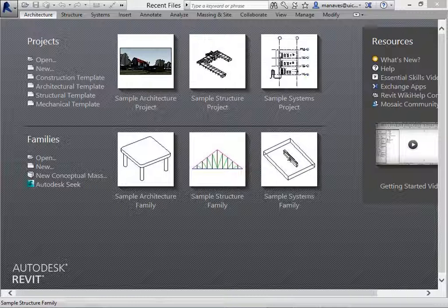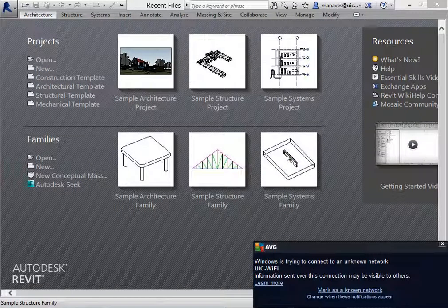So we're working at 1:1, which means 1 foot equals 1 foot. And then that piece of wall is representing a certain material that we can assign to it. We can assign quantities, performance, and then run an analysis or run a schedule of quantities. So it's a whole different way of interfacing with a software because we're building something 3-dimensionally.